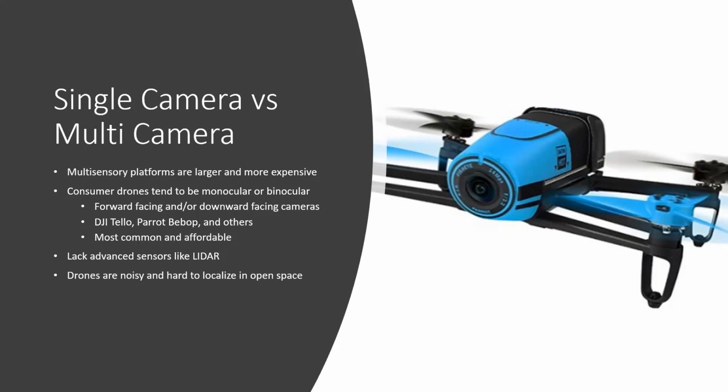So you can't do a lot of this stereo or multi-view type of things like Brandon was talking about, and you have to rely a lot on single cameras unless you want to build your own platform, and that gets very expensive very fast. And because this thing is flying, and if you're trying to do localization like we'll talk about with SLAM, you have to be very aware of how the drone flies and how quickly this communication happens. So offboarding it to a ground station can work for more processor-intensive tasks the drone can't handle because it's so small, but it can induce a lot of latency. So we'll talk about that a little bit more as we get into this.